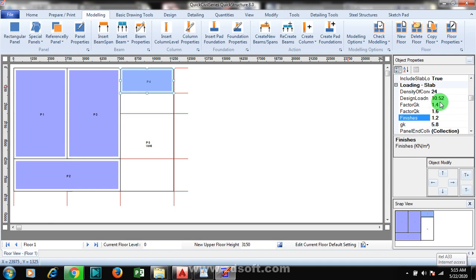Okay, when you multiply your self weight by the dead load factor, you discover what you have. And then when you multiply your live load by your factor of safety, and you do all of that little calculation, you can see your partition allowance here is actually 1.